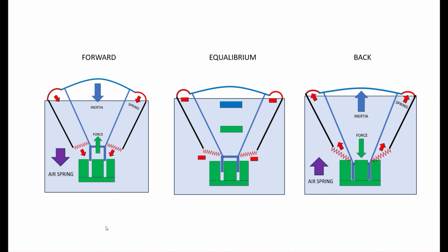Yeah, and if you think about the SPL guys again, the guys are aiming for big dB, 130, 140 dB and more. Putting a stiff spring speaker into a box is fabulous because you not only get the control of the cone from the stiffer suspension, but you now get added suspension because of this extra air spring, right? So in a box you get both the mechanical suspension forces and the air spring forces working on the cone, right? And it becomes stiffer, even more power can be thrown at it, and I can get even louder decibels out of it, right? If that kind of makes sense.